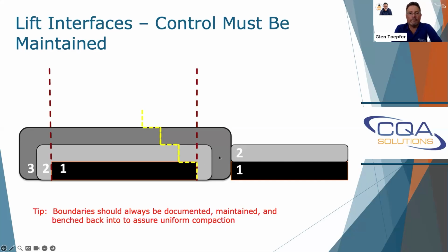I've seen this on landfill cells that I worked on where I surveyed the points, 10, 15, 20 feet sometimes by the time you get up to 6, 7, 8 lifts. And the contractor doesn't want to remove it, but they need to. And you can see once they start cutting into it that it wasn't properly compacted.